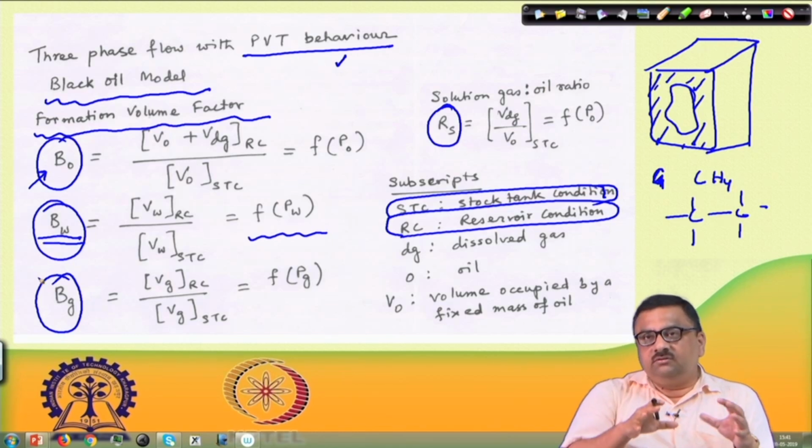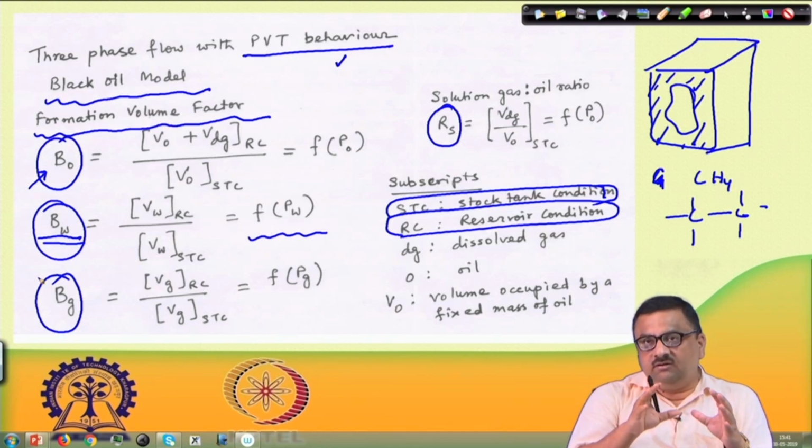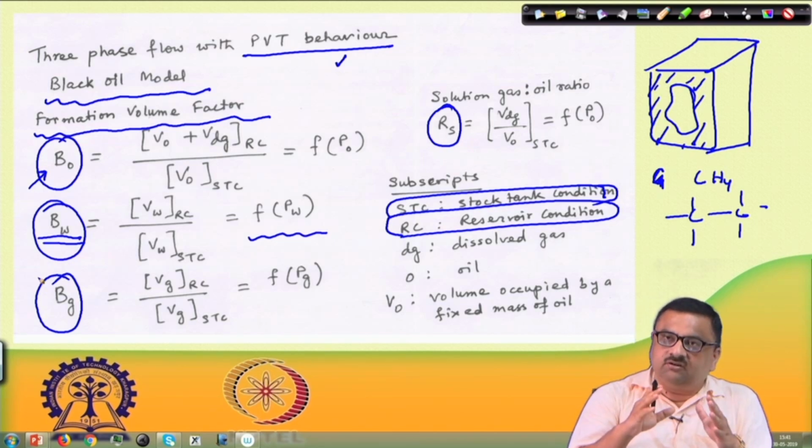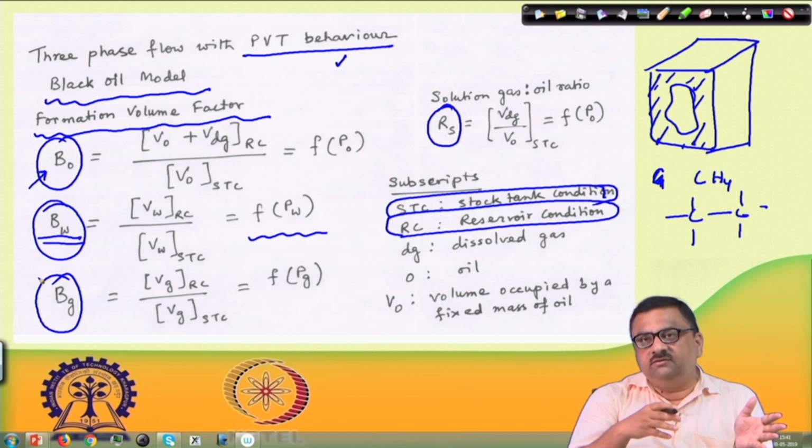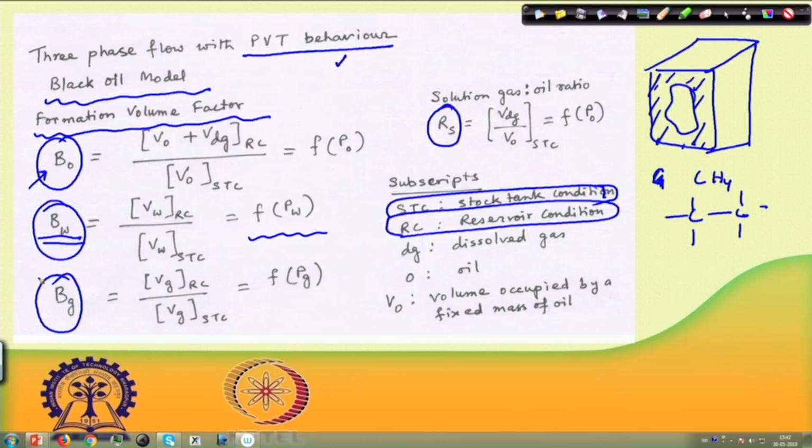Now it would be interesting to see how these continuity equations play out. We will write these continuity equations, instead of density terms, in terms of density at stock tank condition and use the formation volume factor. By that way we can circumvent this problem of using phase equilibria thermodynamics and going for a rigorous solution.